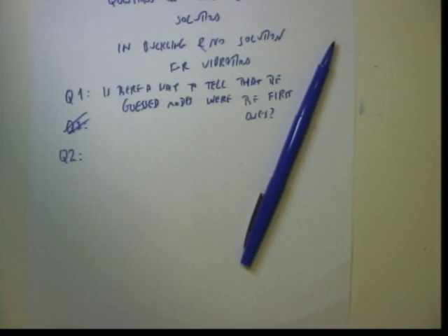Look, please. As we said, we don't have exact solutions of this problem. So there is exact solution given. So the question is, is it the first mode or not? What we have to do is to solve this problem approximately by any means, and then compare the first mode obtained in approximation with this first buckling load. If these two things are close to each other, then naturally we can say that this was the first mode. Or one can say, why don't we solve by finite element method in the computer and obtain several modes? And then if this mode is closest to the first mode, we will say that it was the first mode.